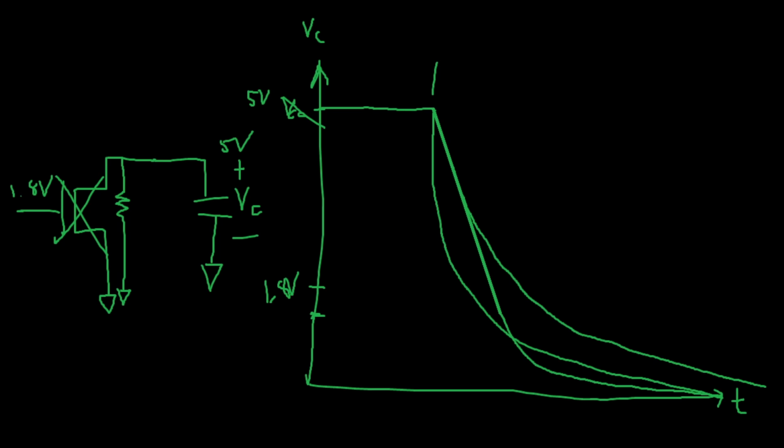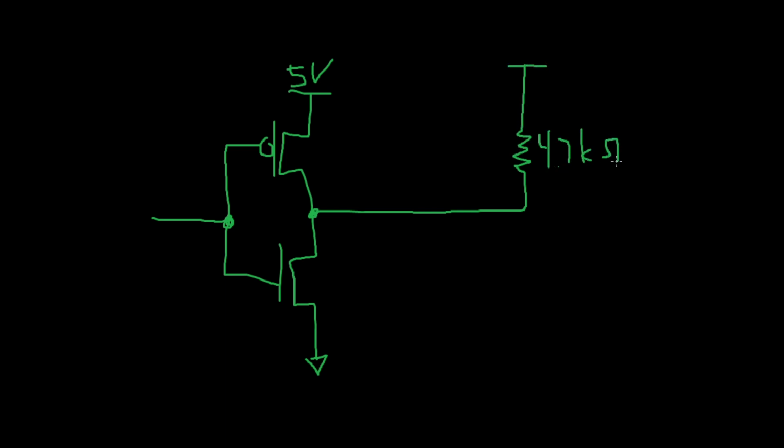One of the most common questions I run into is, how do I determine the output voltage of my CMOS device? So if we come over here and look at a CMOS output, assuming, let's say, 5 volts, and our output is connected directly to our circuit. For example, let's put a pull-up resistor here that is a 4.7 k ohm. And let's call this device perhaps 32 ohms. The question is, what's our voltage out here?